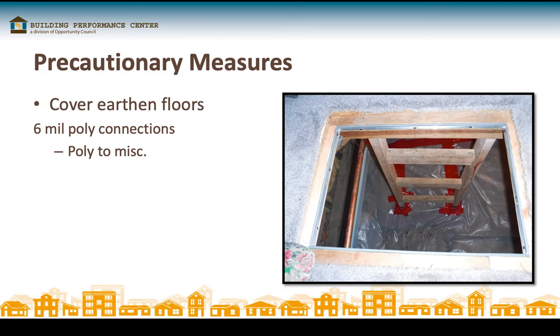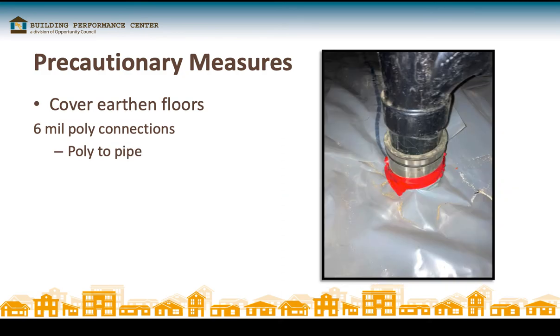And then you've got to seal this poly to anything that comes through the poly. Here a ladder is sitting on top of it, so they sealed around the legs of the ladder. All right, here they sealed around a pipe.